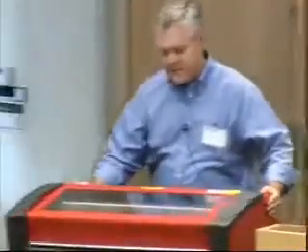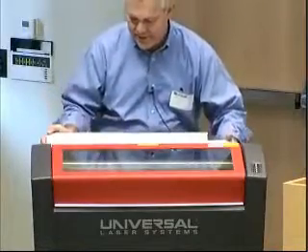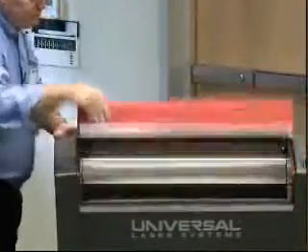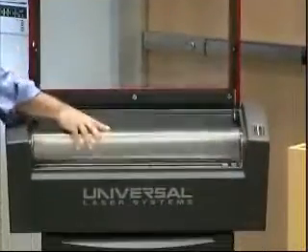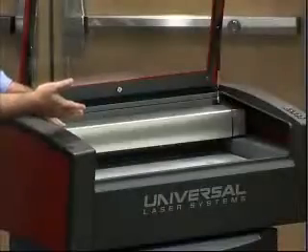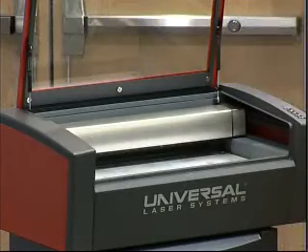This is the laser itself. I'll just kind of point here. There are two inside the laser itself that are sealed. And then this runs back and forth, and this goes back and forth. That's how we get our motion. So the one here and the one here are inside the cutting area. Those are the ones you have to be the most careful of, because when you're cutting, you're essentially burning through the material, and that generates smoke, which is going to deposit on any cool surface and condense out. But just keeping it clean is really the key to consistent performance.